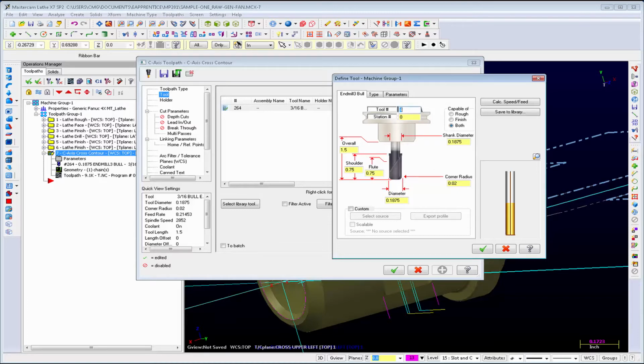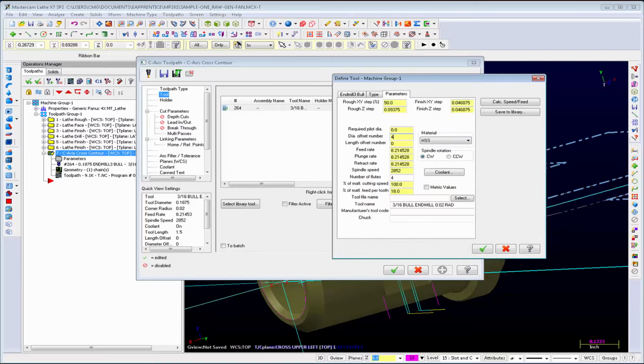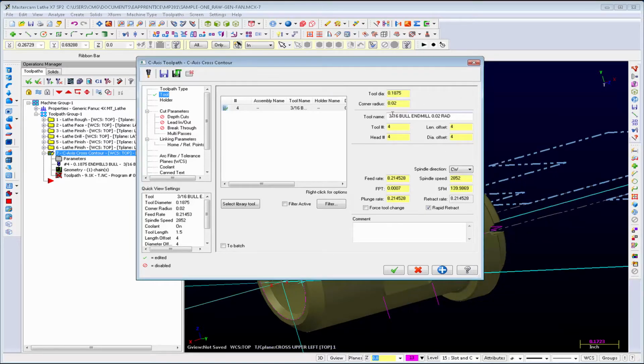Let's just say this is tool 4 and it is station 4. And this is all set up. Good catch, Michael, by the way. So let's set that up. So we're 444. By the way, when you are doing a quote-unquote mill-style toolpath on a lathe, the head number becomes the station number in the post.